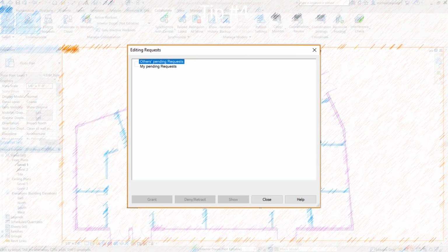And as a side note, a tip: if you're the only one in the project and nobody has any other work sets checked out, you can basically borrow those sets and do your editing and changing. There's just more level of management in here, but if it's just you, you can work as one person and borrow those work sets and do the different things that you want to.